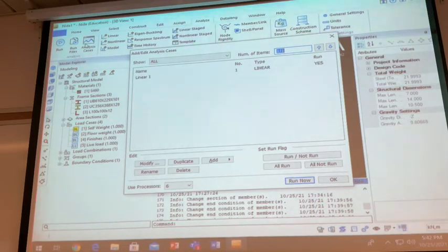As I told you, for nonlinear analysis, even the engineers in big consultant firms find it very difficult to use. Because nonlinear analysis is not that simple, you may experience divergence. How do you solve the divergence? It means that, based on your structural knowledge, you need to work out how to stiffen or strengthen the structure.